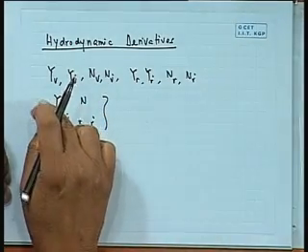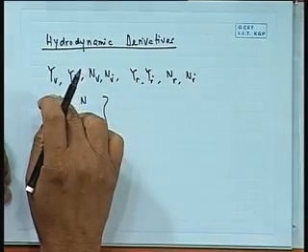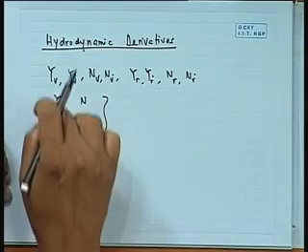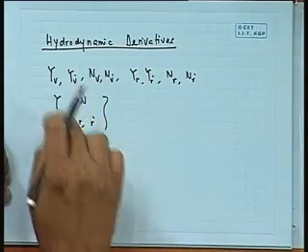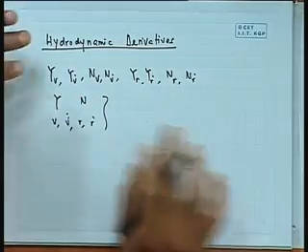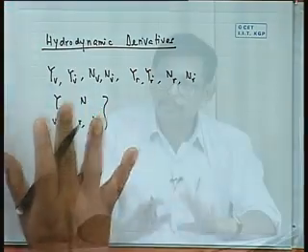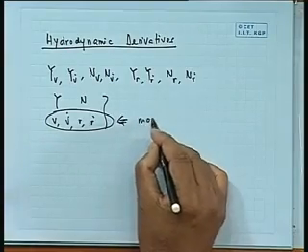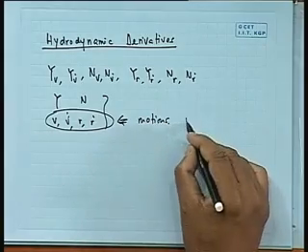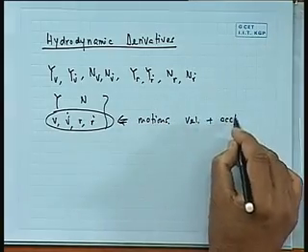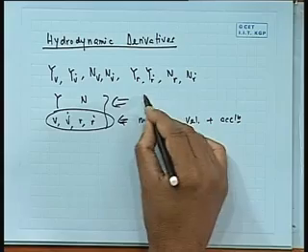Your force against sway velocity, your force against sway acceleration, etc. These are called hydrodynamic derivatives because they represent a hydrodynamic force on the hull because of any of these motion parameters. These are my motions, velocity plus acceleration. This is my force and moment.